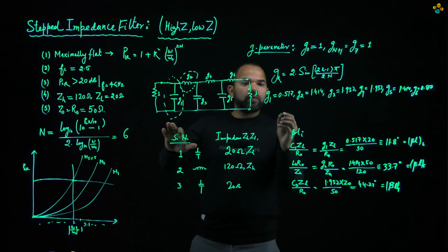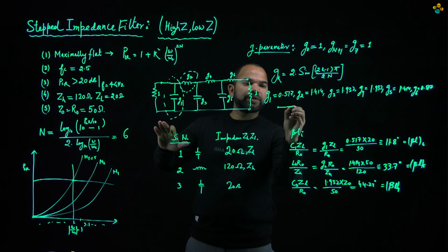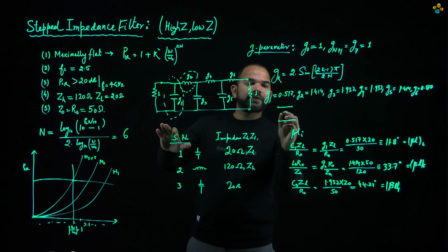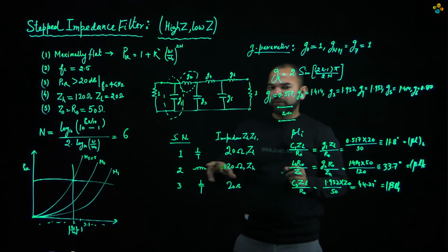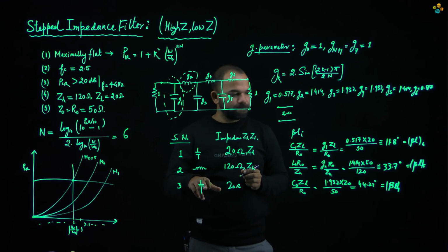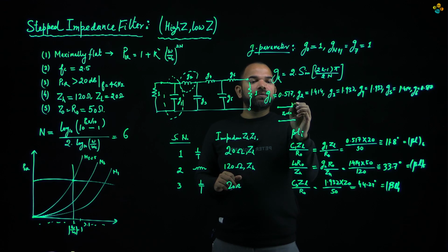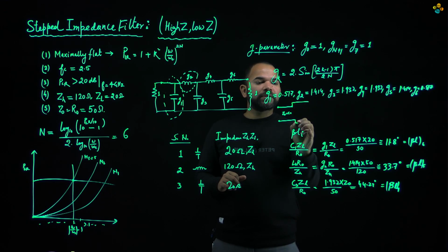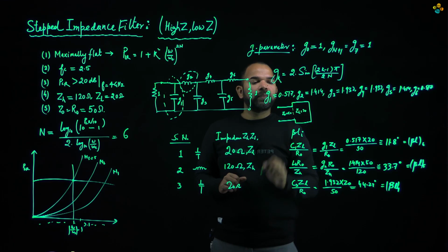So we have a system impedance, which is Z0 equals 50 ohm. Okay. Then we need to design a capacitor, which is a low impedance line. So based on the available space, I'm taking this as Z low, which is 20 ohm. Okay.